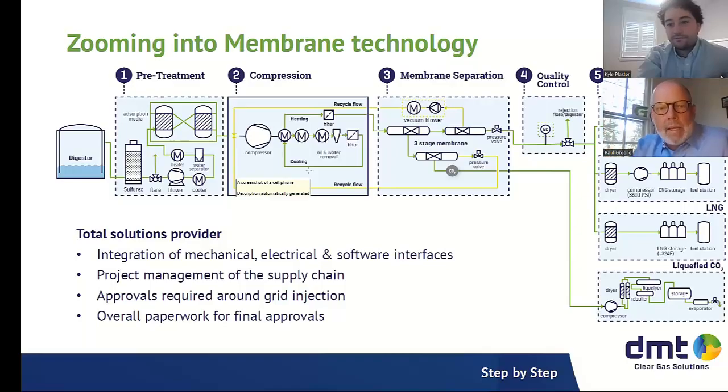So cooling it drops the water vapor out, but that's too cold for the membrane. So then you're just trying to get maybe to ambient temperature before you're getting onto the membranes? Yeah, usually rule of thumb like 90 degrees, but again, the higher, the more permeability. So it's really just what you're targeting on that first stage.